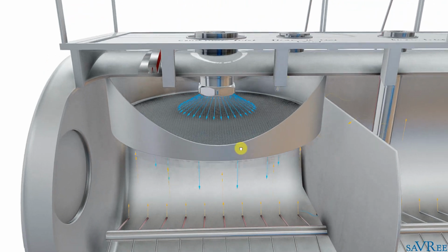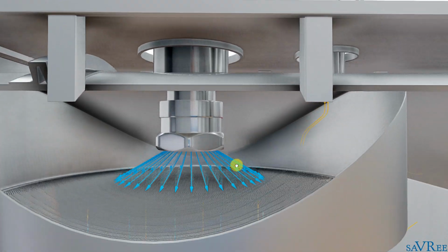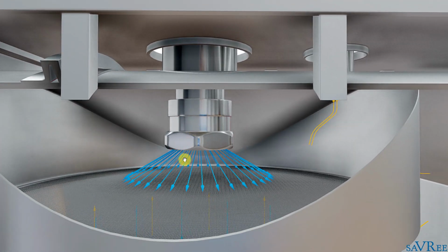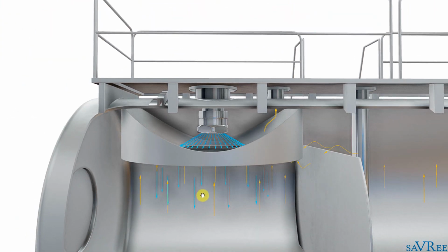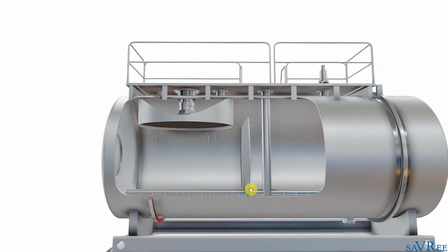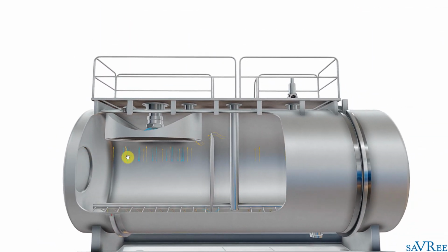It's going to be sprayed out of a spray nozzle, which is represented by this section here. And we're going to spray it into this spray area, and it's going to drop down, and then it's going to gather in the lower part of the tank at about this level. And at that point, our condensate is now classified as feedwater. The tank itself is a boiler feedwater tank, although people will often call it a deaerator tank.